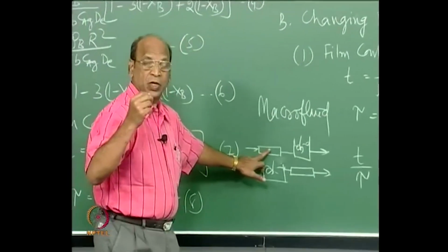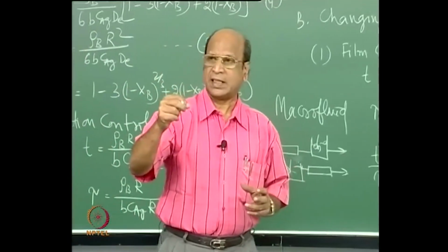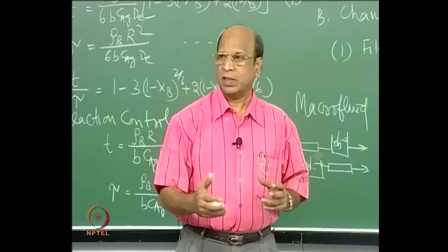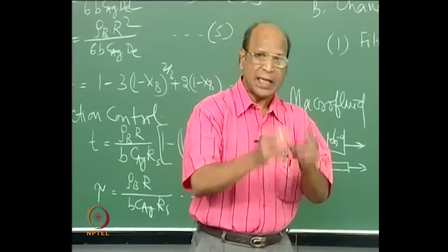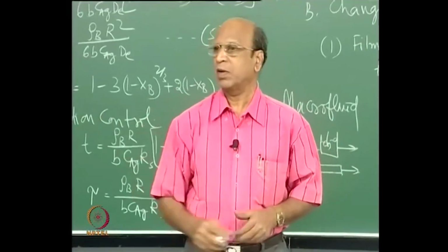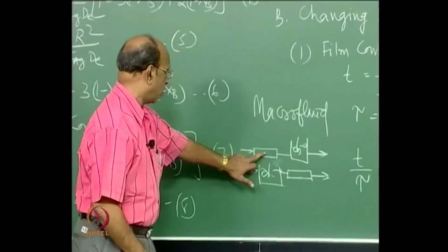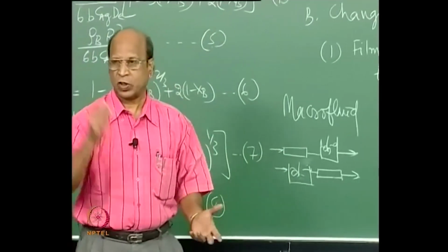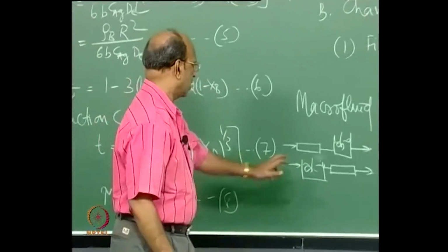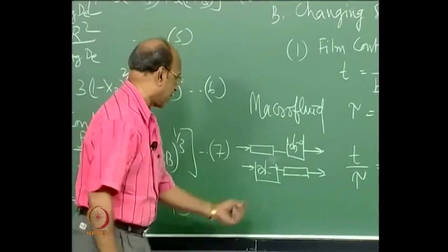That means, you should not allow mixing for higher order reactions, greater than 1. You should not allow it in the beginning itself. So, that means, you should delay the mixing as much as possible. Delay the mixing, here it is delayed. First I have plug flow, where by definition there is no mixing, we are talking about axial mixing. Okay. Good.